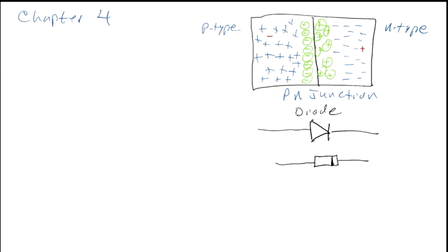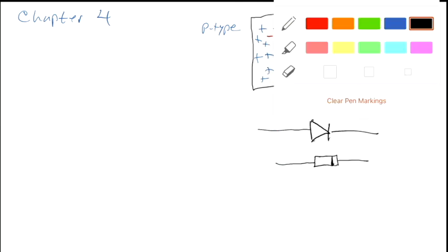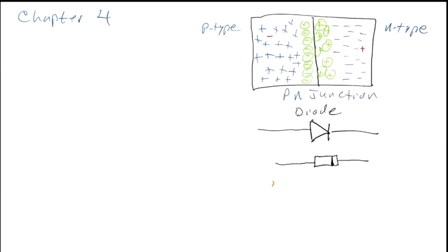If it's an LED, there's one way that you know is the high and one way is the low. And I never remember which it is. The short leg is the ground or something like that, the low side. So that means the short leg is this side. And when you turn it on, the long leg has a higher voltage. That's this side. And we've got names for those: anode and cathode.